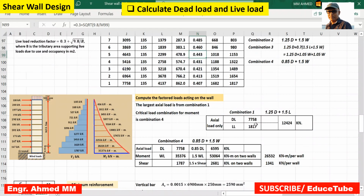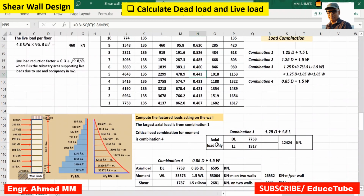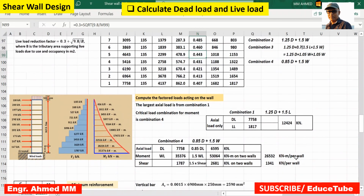So the second part of the video will be up to this, to calculate total axial load, I mean these dead loads as well as live loads. This one already I showed, this wind load, but here I have shown how to calculate for one wall, and this is shear. So we are up to this level now.